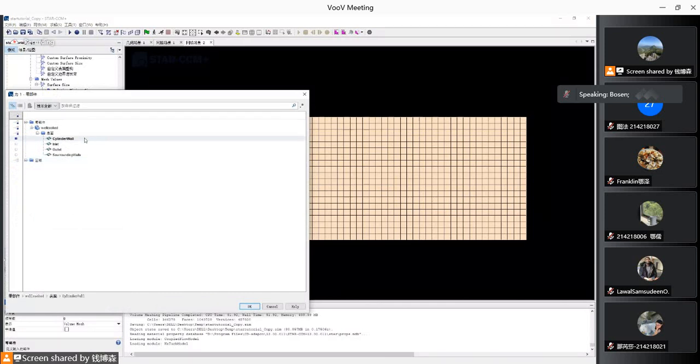Okay, so that's why both the cylinder wall and the surrounding wall are wall structures, but in the surface definition we separated them. It's not because it's redundant, it's just because it's necessary. Otherwise, in the monitor system, it will be impossible for you to monitor the forces solely on the cylinder.